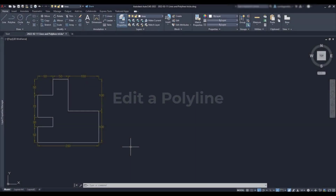There are several features we can edit in a polyline, and we are going to start with close. To explain this situation, I'm going to use this example where we are going to draw this simple figure with the command polyline. You will see that what matters here is the way we will draw the last line. Let's activate the command polyline. As you may know, I can click on the icon at the ribbon, or a faster way is using its alias. Just type PL and press Enter.